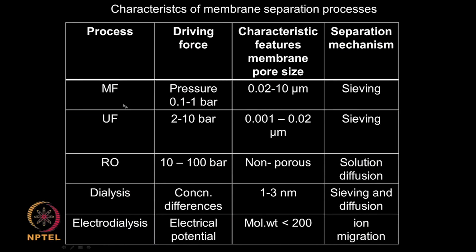So, these are the driving forces by which membranes operate. If you look at microfiltration, generally the pressure is of the order of 0.1 to 1 bar, and the pore size is generally 0.01 to 10 micron. And what is the principle? It is based on sieving. That means it is almost like your filter. It captures or retains large particles and allows particles of smaller size. So, that is the microfiltration.